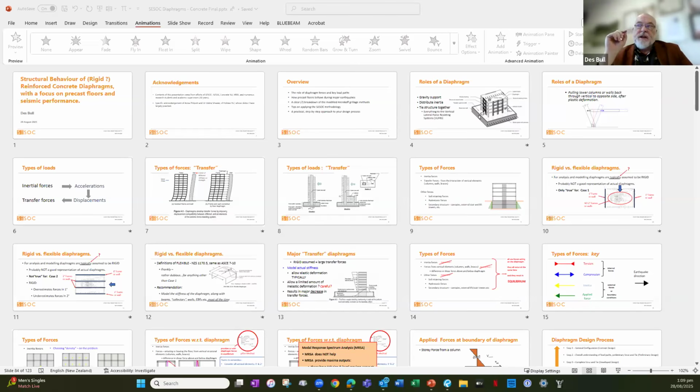The reason is that, going back to the 1994 Northridge earthquake in LA, when they opened up a number of buildings which had mesh in them, they found that the mesh between every unit was fractured. Every wire between every precast unit, all the mesh was gone. That was Neil Irvine and others who found this. Possibly these were in car parking structures, so car traffic and heat and cooling of the day caused high cycle fatigue on the wires. But they opened up other ones. We did this here in 2010, 2011. We opened up floors and found in the middle of the floors the wire mesh was broken. So generally between units you can't rely on it.